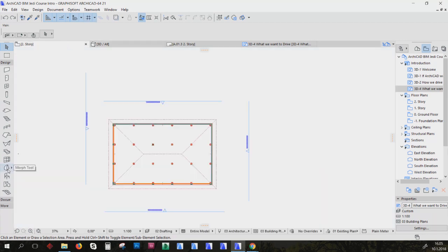Gravity. Does everyone know about gravity? Not Newton's gravity, but ArchiCAD gravity, and how you can place objects on top of slabs, roofs, meshes, and something else. So if you've got a roof and you want to put an element halfway up it, you can turn gravity on and it will put the element on the roof. It won't stick it up here or down here, where you've got to go and work out where it is. It'll fix that point.